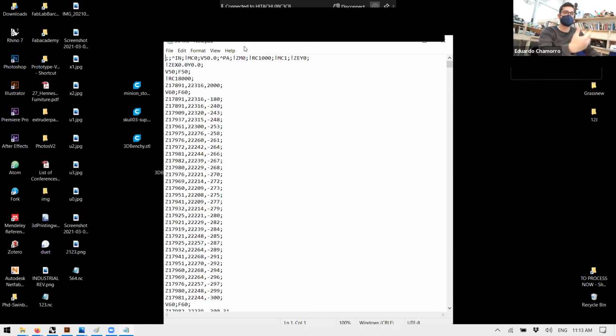Like most of the decent CNCs, or more or less professional CNCs, the interface of the machine is not just a gamepad. It's a gamepad and it's showing you how it's loading each line of code. So if something bad happens or you want to stop the machine, you can stop at this line, know exactly what is happening, and maybe skip another line or move back 3 lines. So you can stop and roll back on the code.